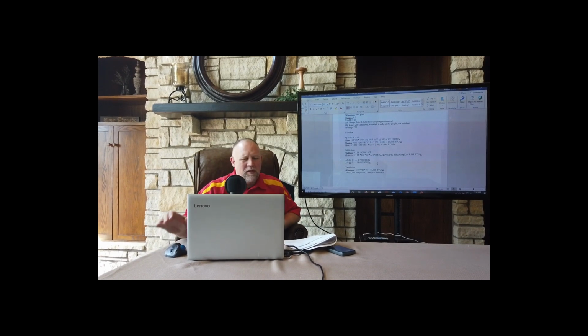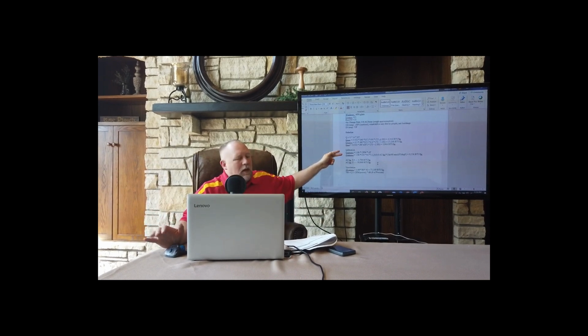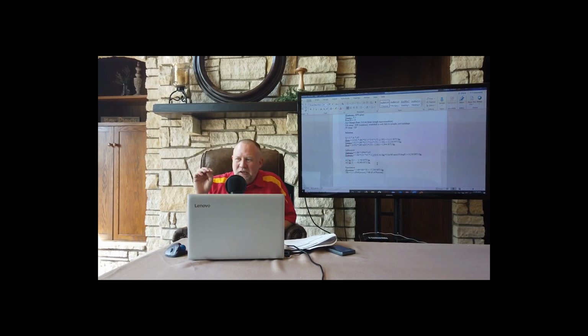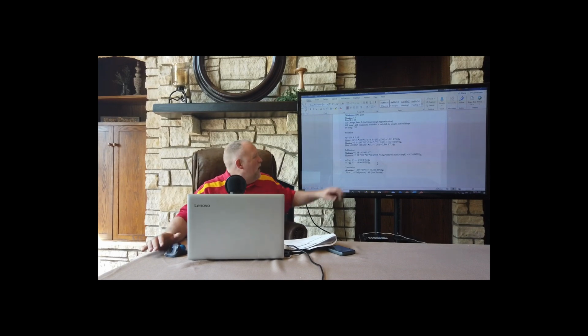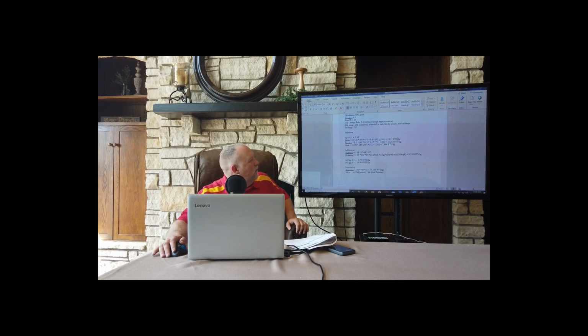Now, something important to notice here, this infiltration is a total guess. Let's back it down to 0.3, right? I mean, now look at the magnitude of these numbers. Just calculating the numbers is important, but I also want you to think about the magnitude of the numbers. Each of these U values is like so-so, okay, but notice the roof is easily the smallest value.